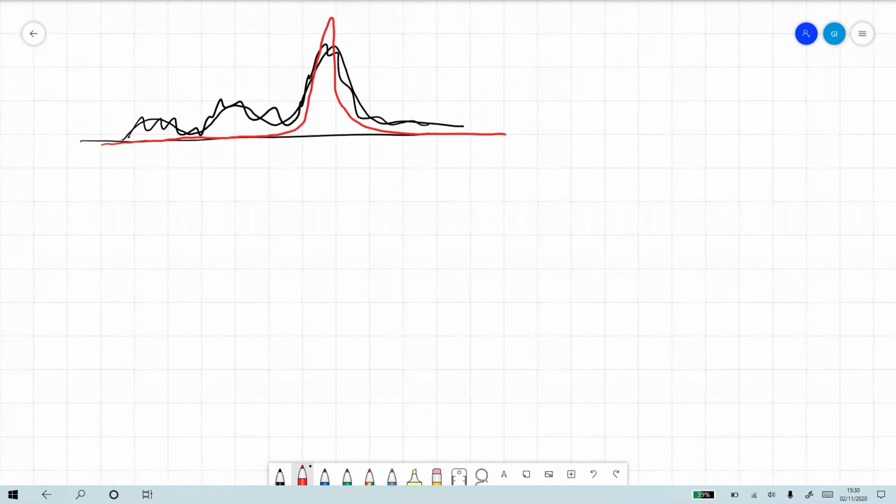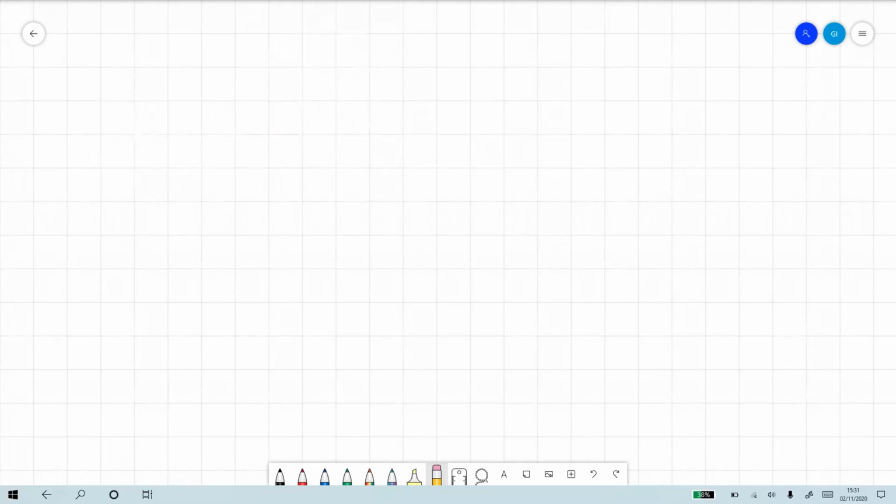We want to design a circuit that receives many inputs on many taps, like we had with the Gilbert normalizer, and selectively amplifies the stronger inputs with a gain higher than 1, and selectively suppresses the weaker inputs with a gain less than 1. Now, how do we do that with analog circuits? Well, you can imagine it's going to have to deal with current conveyors and Gilbert multipliers. So let's start again with the classical current conveyor.